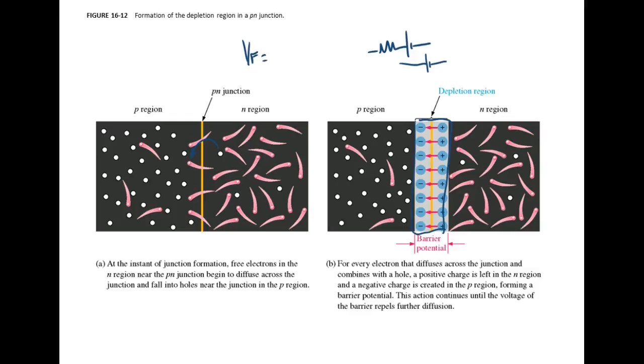So I could take a 9-volt battery and put a resistor in series, and I could hook this up, and then we would measure approximately 7/10 of a volt for silicon. Now notice I'm saying approximately, because it has an R and it varies with current. So this is what we use. Some books teach 700 millivolts, so most people say 0.7 volts.